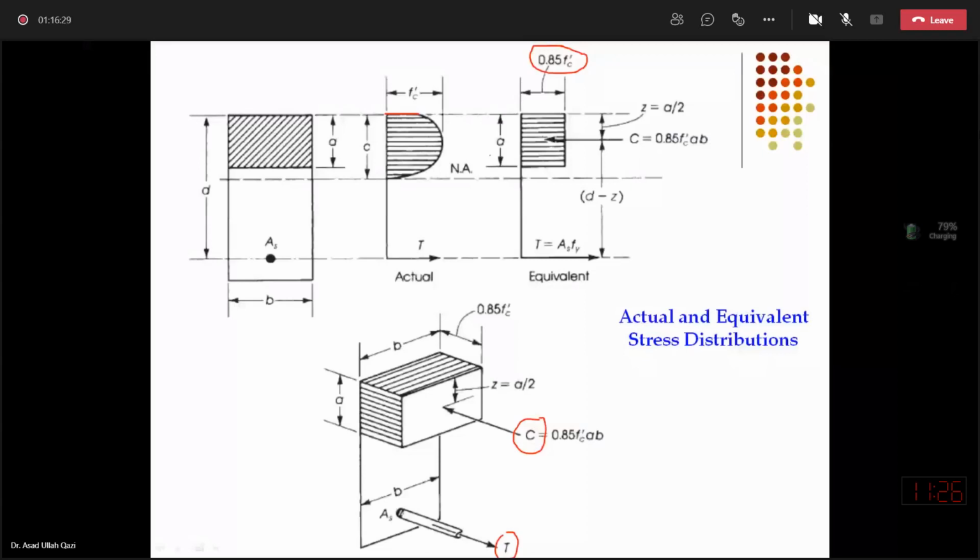So we have mentioned all these steps, but we remained silent on what the status of the steel was when crushing is approached in the concrete. Whether the steel has yielded or is below yield, whether these bars will have As Fy, which is the limiting strain, and in USD we will use a maximum of Fy; the stress in the steel bars we will use in our equations is up to Fy. So the maximum T we can use in our equations will be Ty, that is As into Fy.